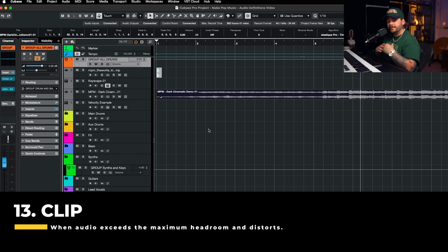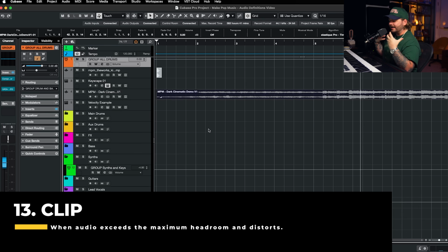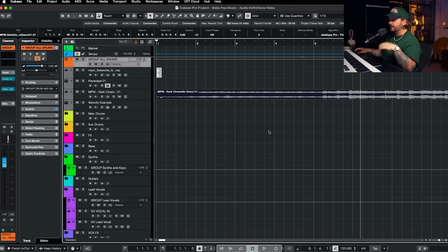A good example would be if I'm talking into this microphone. I'm at an okay level right now. Everything's feeling good. But if I scream really loud in it, it might start to get that kind of distortion, that clipping, that artifacting. You can't really undo that later in the process. Once audio is recorded and it's clipped, you're kind of done. So make sure that when you're adjusting your gain, you're not clipping your audio. Make sure that you have a healthy signal that's not too hot or too loud, because you could run into issues with clipping and saturation.